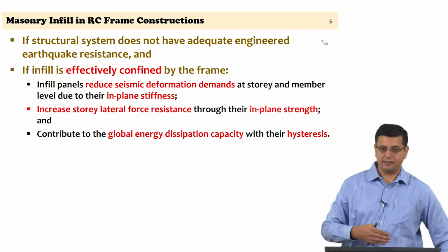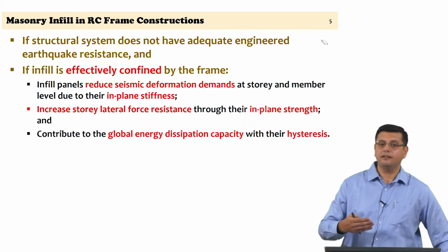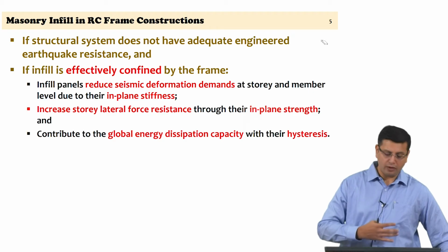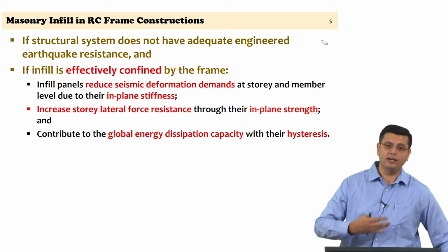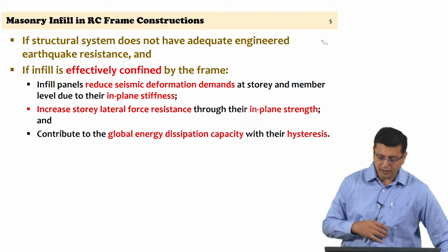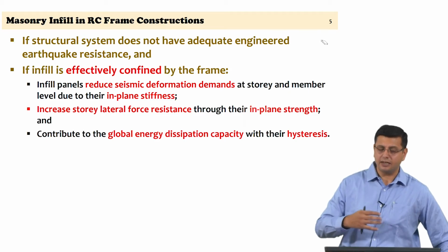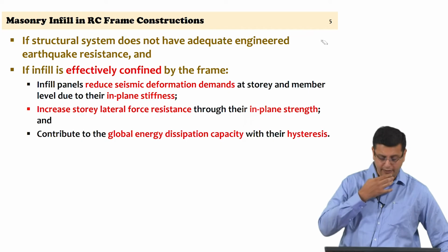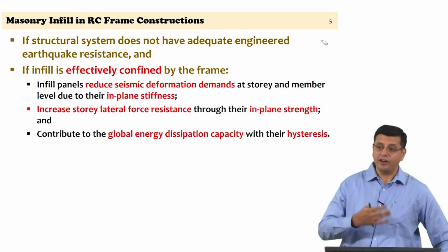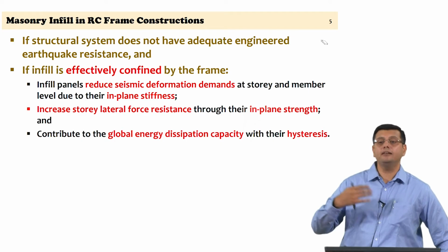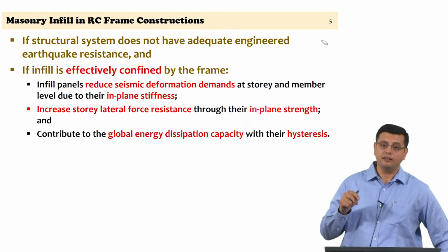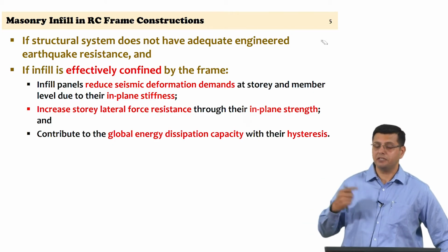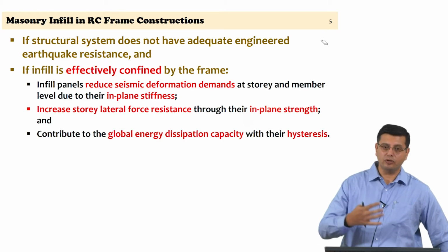In the Indian context, often we have seen that since the quality of bricks is typically poor and workmanship is also poor in the rural areas, in the semi-urban areas where construction procedures are not thorough, the frame is very often protected by the damage occurring in the infill panels, and there is a dissipation that comes from the panel, which then in a way protects the overall frame.